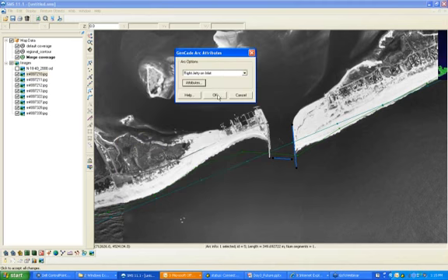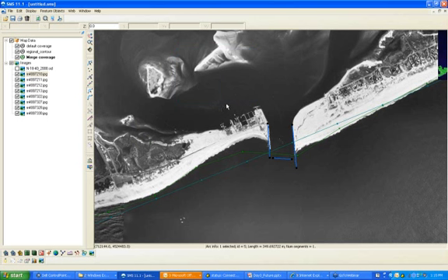Another thing you can do here is, say you've drawn your jetty and it's not in the right location for what you want. You can always move this around in the conceptual model. And how you would do this is by going to the Select Feature point. You would click on this point and you can actually drag it around to the new location. So that's a simple way to make changes to your arcs without having to delete them and then start over.